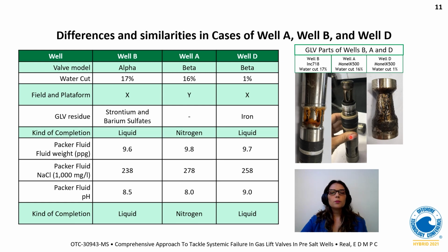However, it was not possible to dismantle it. There was no tool for it at that time. Thus, it is very unlikely that no residue deposited in the internal part of this valve, since it presented a check valve stuck in an open position, like in this picture, and this indicates the valve failure. One possible cause of this type of failure is residue deposit in the check valve.